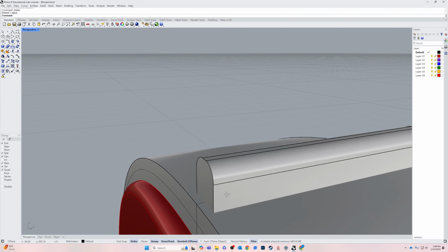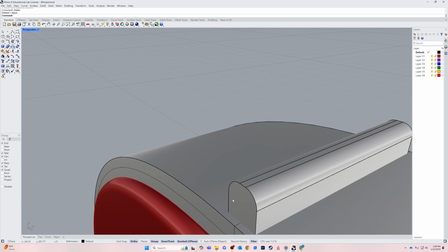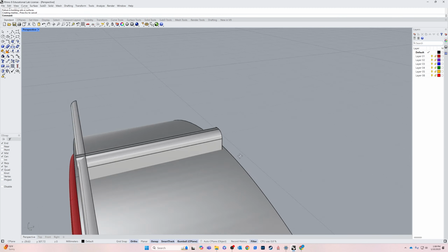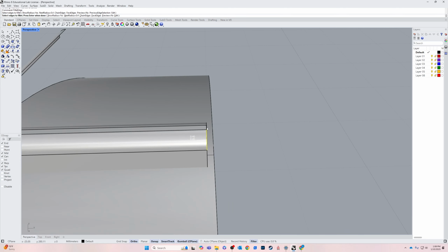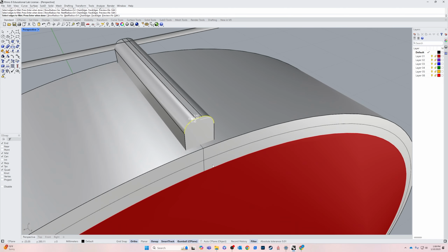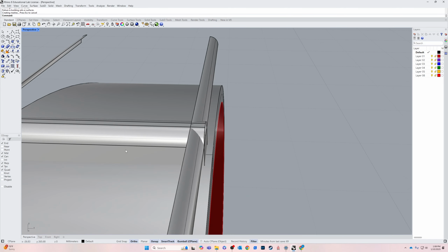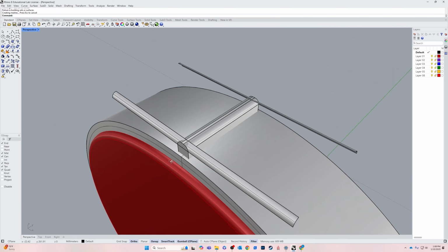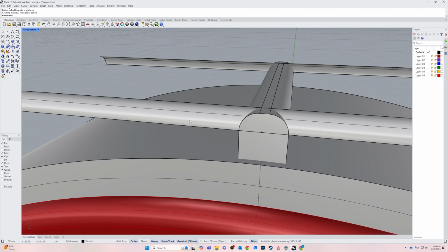And then what I want to do is fillet the front of this. So fillet edge this time because we're dealing with a 3D object. Enter. And then I want to do a radius. 0.4 is fine. So I'm going to select this, this, and this. Enter, enter. Okay. And then I'm going to do the same back here. Select this, this, and this. Enter, enter. Okay. And you see, it didn't actually round those sections because it had problems doing the math.